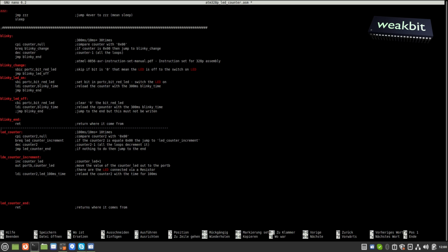We increment the counter, we move the counter out, and we increment it. Should we load it? No. After 100 milliseconds, it's running in, it's 0. We increment the counter, we move it out, we load the 100 milliseconds again. And then we are returning. This is finished now.